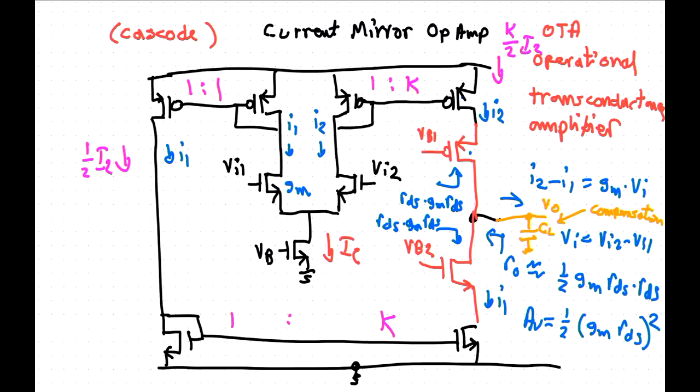But yeah, the premise is, if we want to have most of our current in the diff pair, because that's where we get the best bang for buck for noise, what we've got to do is to make K smaller than 1. And then probably make this one K as well. And if this is smaller than 1, then the gain from here to here suffers by K. We're scaling down the current driving capability for that.